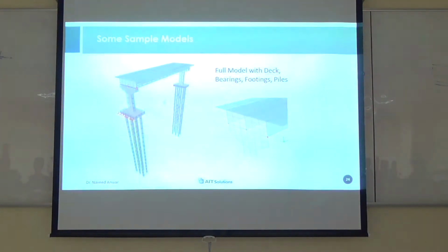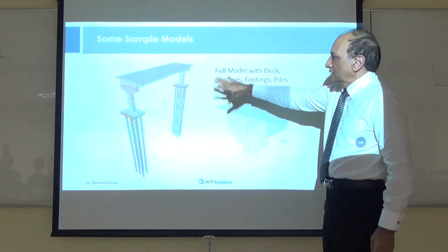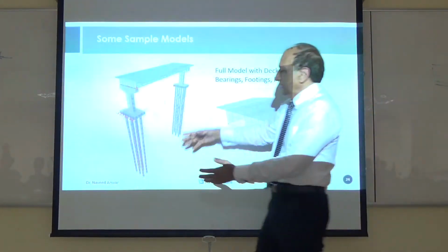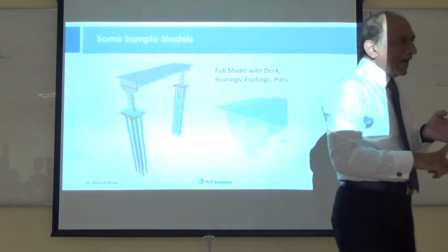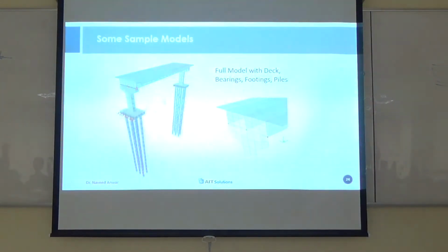So this way you can analyze it, and in one go you can get the forces in everything. In the slab, in the girders, in the diaphragm, in the bearing, in the pile cap, in the pier, and in the piles themselves, and soil pressure also. All in one model.